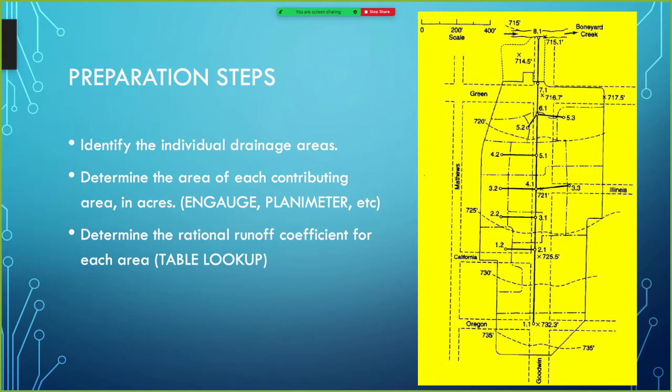Any graphical manipulation tool that has the ability to measure areas is adequate. To some extent, the units don't actually matter because we'll do arithmetic to handle that. We also are going to need to determine the rational runoff coefficient for each area, and that's a table lookup.